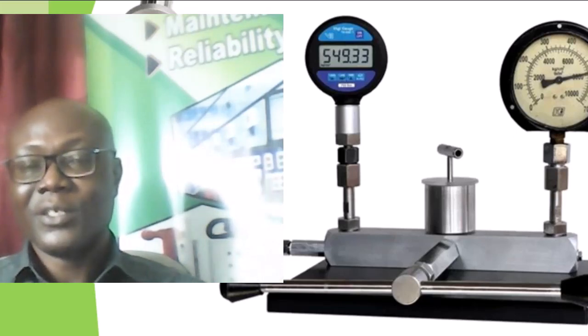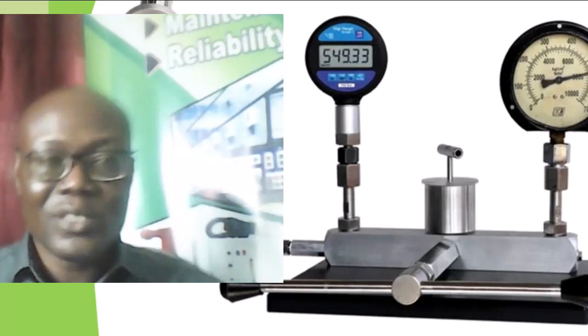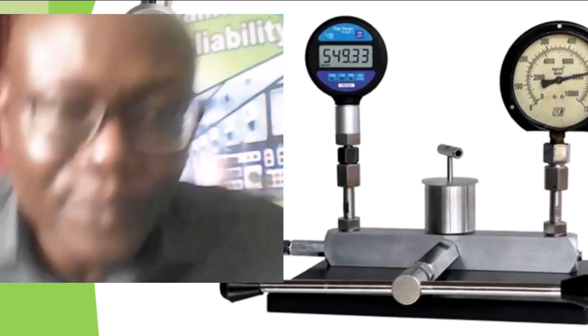Are we getting it? If the deviation from what is normal is tolerable, which will be stated in the data sheet of the instrument, fine. If it is not, then we need to replace it, okay?